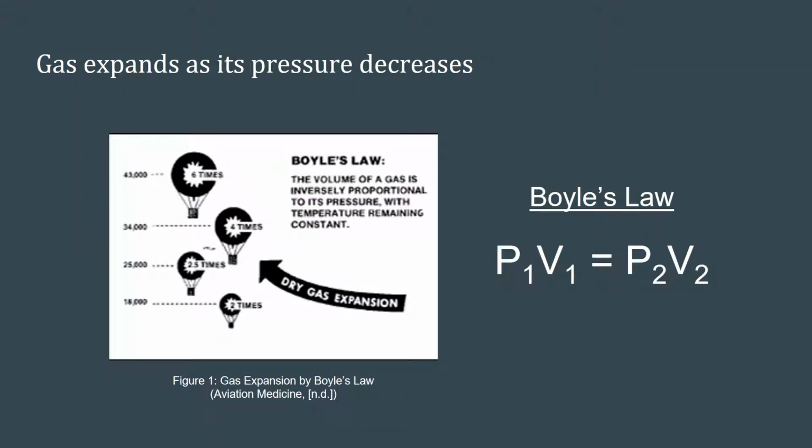One of the biggest issues with offshore drilling is the possibility of a gas kick entering the drilling marine riser. If a kick enters the riser and passes the BOP, you lose the ability to circulate that kick with the choke line. As a result, the kick must either be circulated out or allowed to migrate on its own. Either option results in gas expansion.